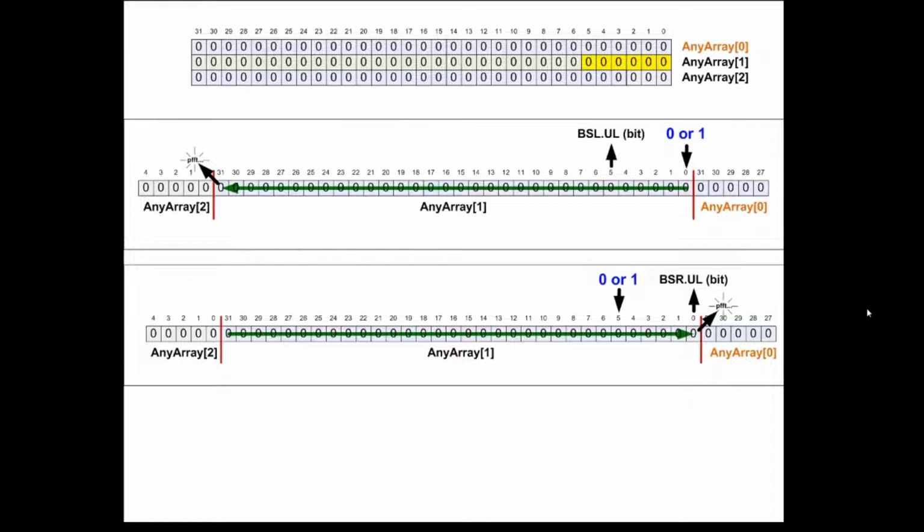So without a 0 there, you're not going to get the part added to that larger assembly. The bottom one takes a little bit more thinking about, because there really shouldn't be any values in bits 31 through bit 6 of that lower array 1, because you're not putting in any values. So they should start out all zeros, so you should see nothing but zeros marching across to the right.